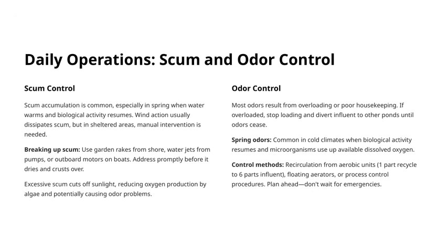Remember, excessive scum can block sunlight from reaching the water, which reduces oxygen production by algae and can lead to odor problems down the line. Now, moving on to odor control. Most odors are caused by overloading the system or poor housekeeping practices.